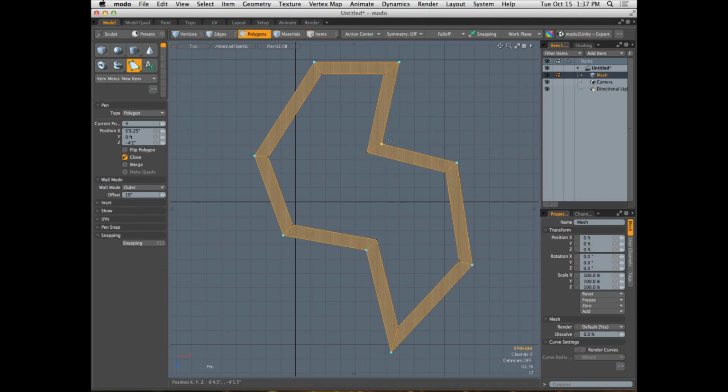And while the tool is still live, we can continue making changes to the dimensions of our walls. So if maybe we flush things out at 10 inches and then we decide, man, they need to be 6 inches, well, if the tool is still live, we can just reset those values and the walls will change and update on the fly. So it's a pretty cool system.